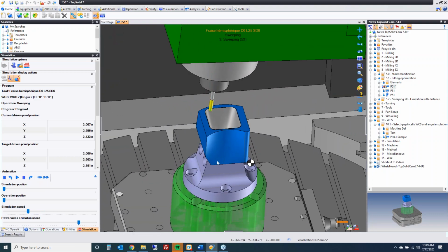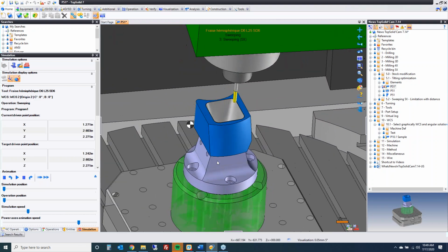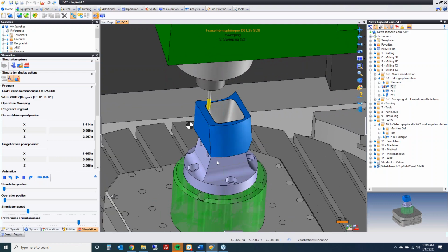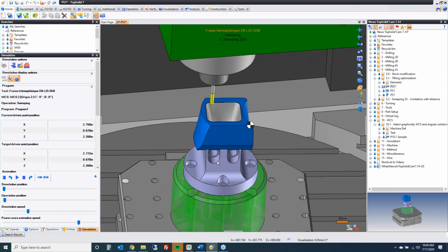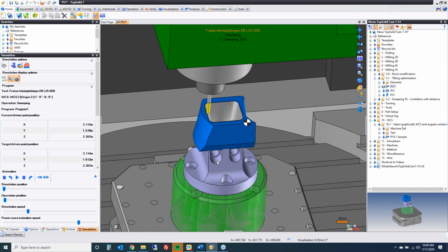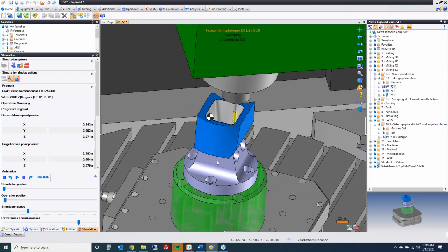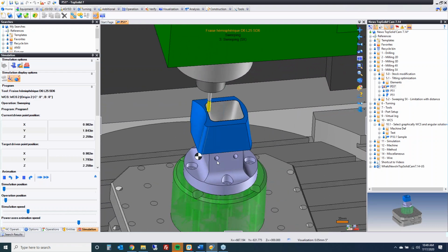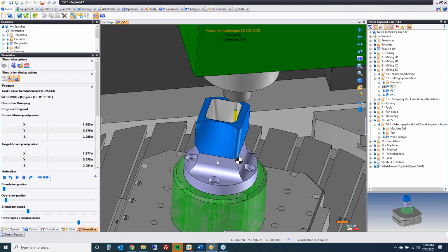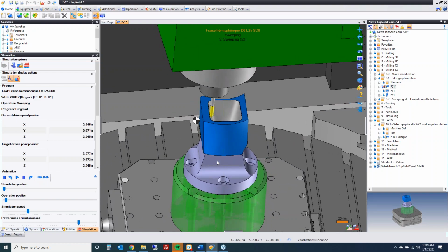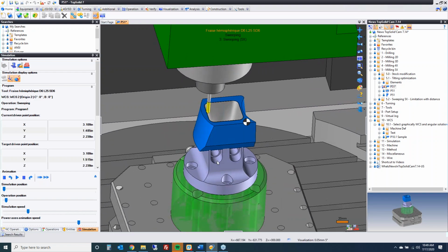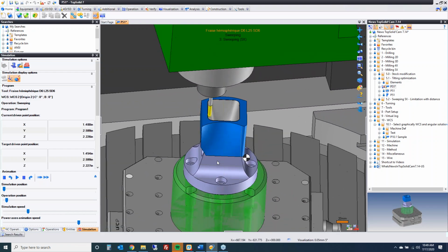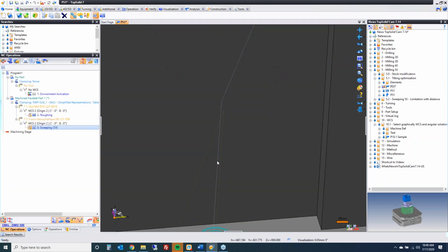All right, so if we watch this cut, we're keeping an angle here, and you see how the tool is spinning the C-axis in crazy ways, okay? And the reason it's doing that is because there is a slight deviation between normals as you go around the corner, and so it thinks, oh, I have to go all the way around to the other side, okay? And that's just not always the case. Sometimes it is, okay? But when it's a slight deviation in normals, it would be cooler if we could control that to keep the part a little more stable during a 5-axis continuous cut.